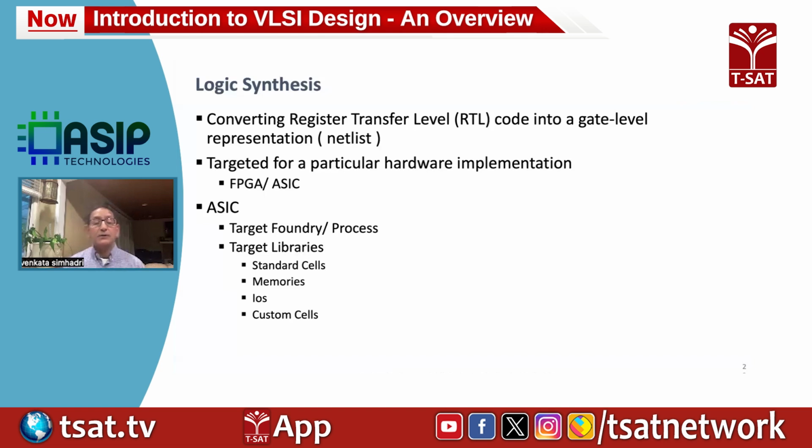Is the SoC going into a TSMC 28 nanometer process or a 5 nanometer process? And once it is targeted towards a particular foundry, what are the libraries you're using for the synthesis? When you're converting that into logic gates, inverters, NOR gates, NAND gates, flip-flops, you're not designing those cells from scratch. There is an existing library of cells you tell the synthesis tool to use.